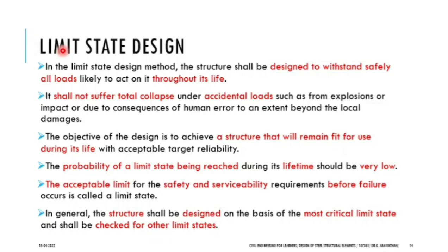If you want to build your house, we will ask where is your location. Are you building in Channapatna? Are you building in Ramanagara? You should check that. You have the zone for your district. Check your zone. And you should take the zone and you will be taking how many loads? Dead load, live load, wind load, earthquake load. So these are the 4 loads you should take care of, and then you will start constructing. So this is what limit state says: if you are taking all the loads, can you find the stress? Okay. The rest of the things I will continue in the next class.